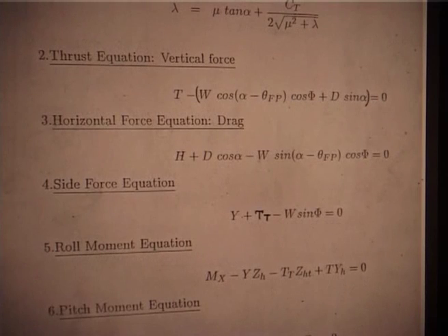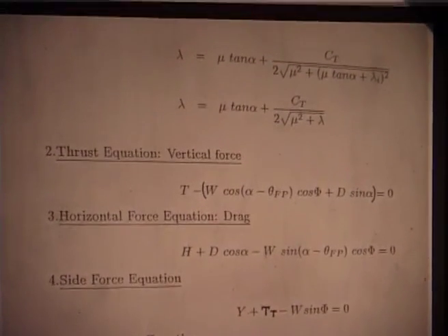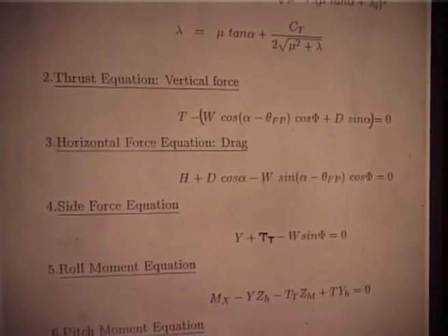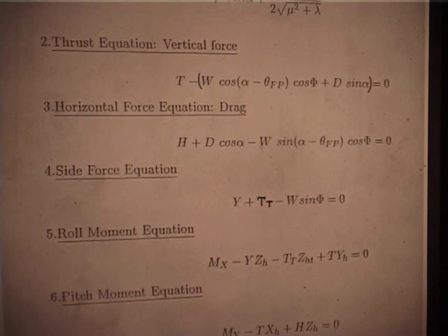Where is the flap equation coming in between? Because the flap equation is sitting somewhere, because all these thrust, H, Y, Mx, My, they all are dependent on flap response. Now, flap response we approximated as the first harmonic, beta naught, beta 1c, beta 1s, and the rest of them we neglected. So, all these expressions require flap. So, you have to now introduce the flap equation in between.